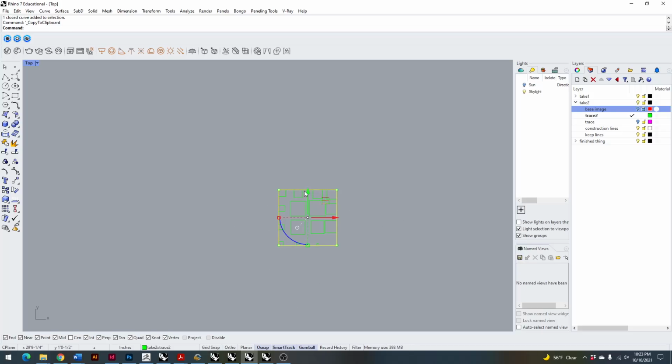So we'll copy and paste this bounding rectangle, Control C and then Control V, and then we'll move it up 8 inches. And that just moves it so it shares an edge with the plan. And then I like a little bit of space between, just to give my elevation some difference from my plan. And so I'm going to move it 2 inches above. And it's important that all of your elevations are the same distance away from the plan. And I just mirrored it across the central axis.